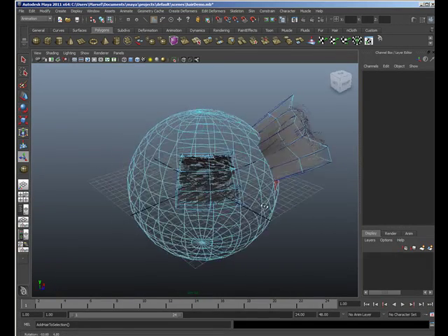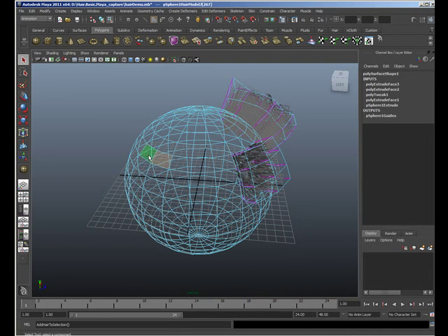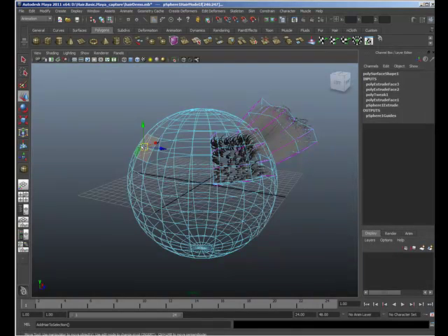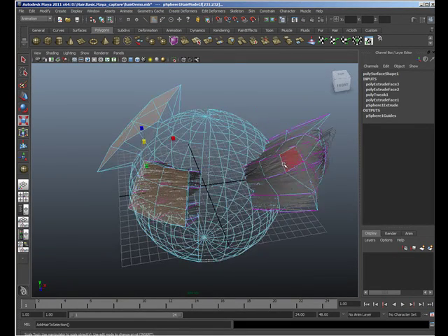The extruding process does not have to be uniform. As long as we call Add Hair to Selection on proper faces, we will get predictable results. In fact, we do not even have to extrude at all. We can achieve the same result by just pulling off some faces and calling our function. Hair.Basic is smart enough to identify the changes you make to the mesh and fill them with hair.